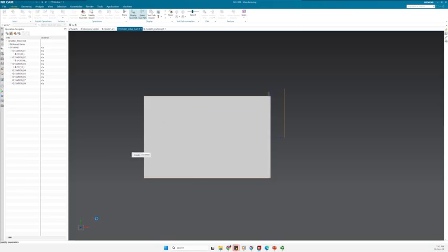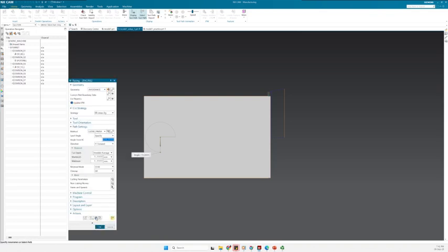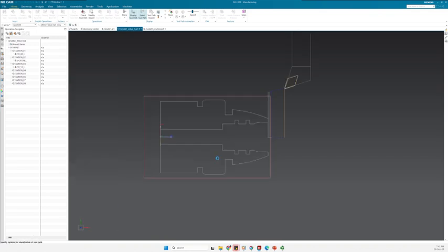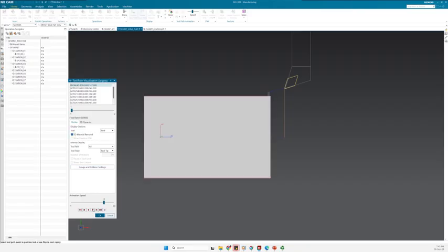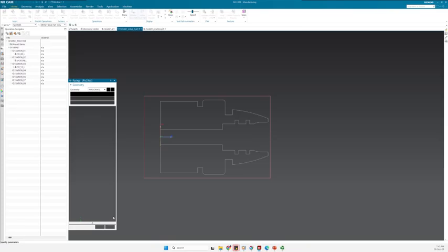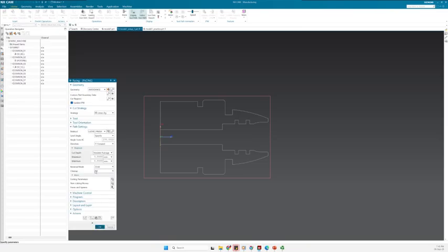The toolpath is now generated, and then I can verify that one. It looks okay, but let's figure it out. I can again click this one so that I can see the actual material removal. Now it works fine. There is no collision, no wrong tool pass. So this is fine. The next thing that I need to do is to figure out what are the machining process parameters that I'm interested in.